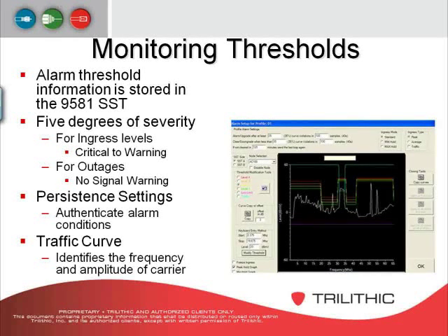which is usually an alarm that, if you need to have everything at a minus 30, then if this gets to a minus 29, it hits level 1 and sends out an alarm. But that's not enough to knock out the system.